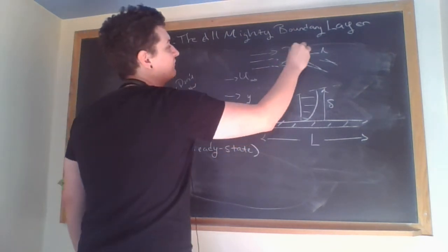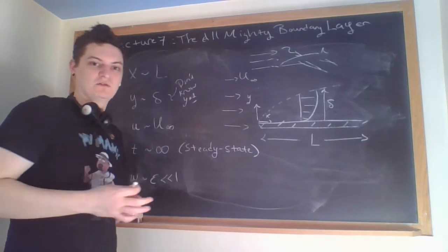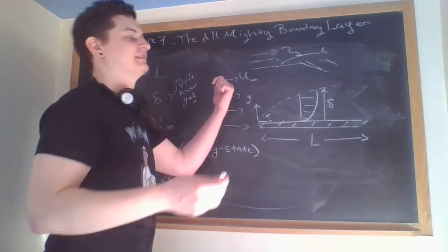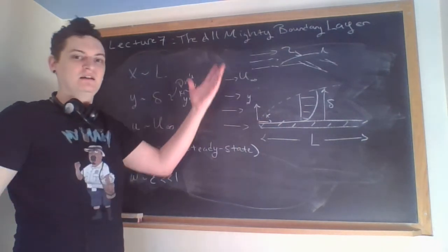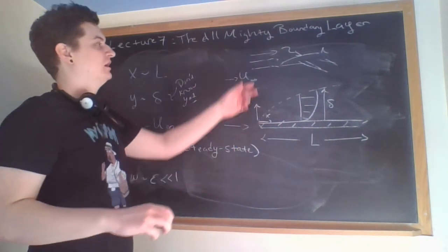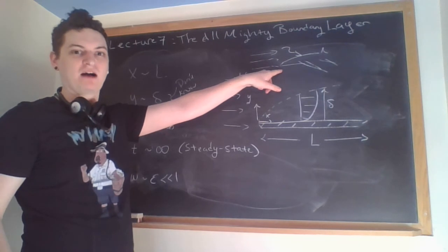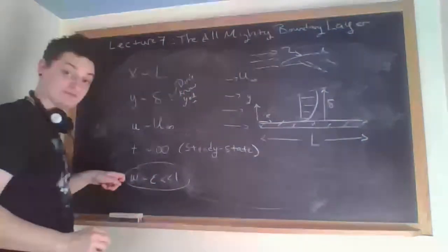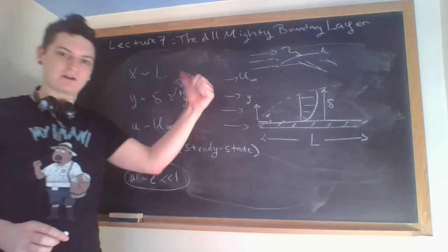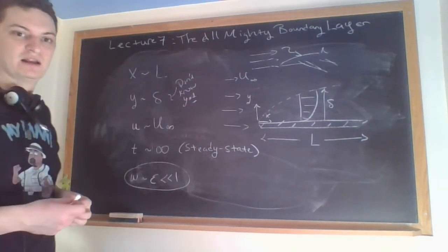We don't have cross flow over it. We're going so fast in this direction that maybe there's a little bit of a gust of wind, but it's nothing much at all. Really, the dominant flow is the 500 miles an hour wind hitting it. So there's a lot of reason to justify that the in-and-out-of-board velocity is totally puny and negligible.